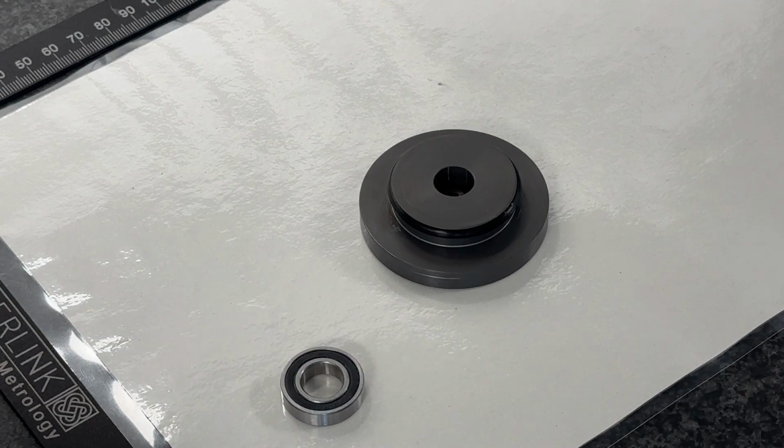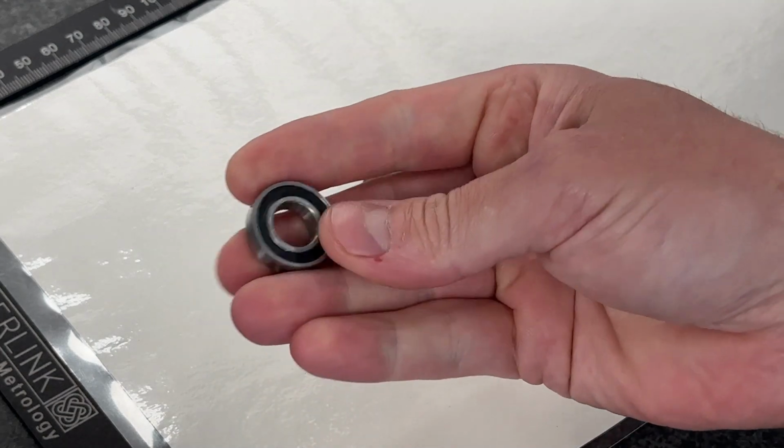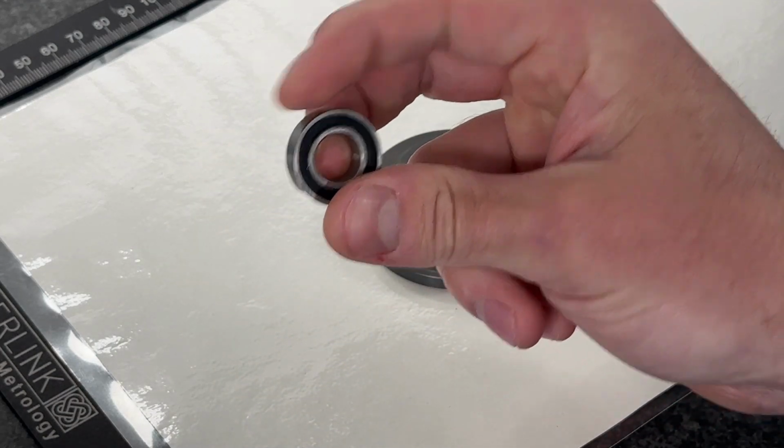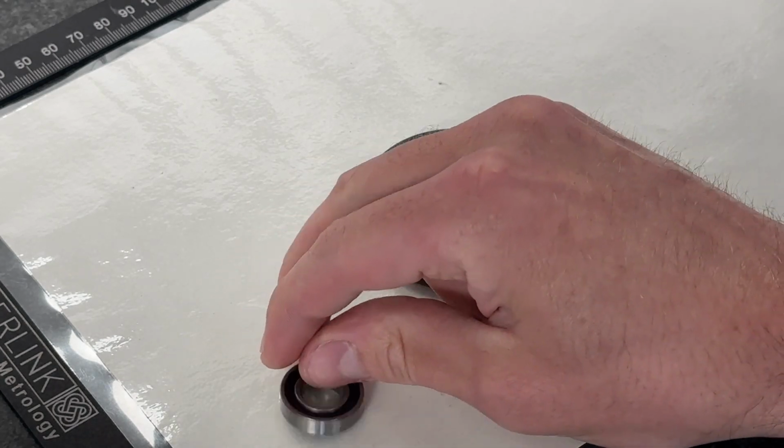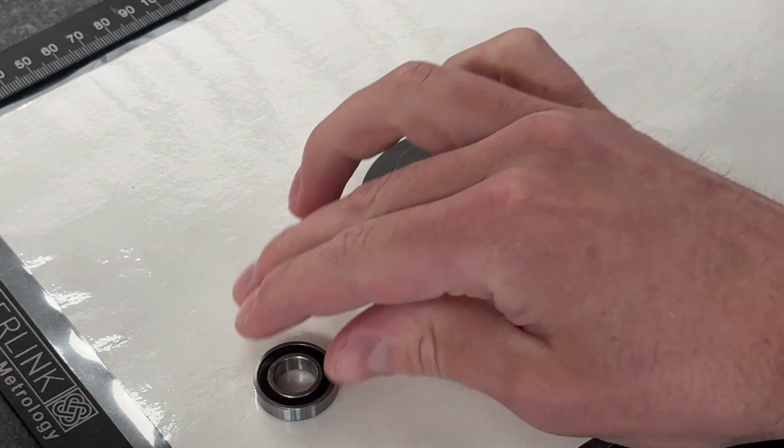Before we get started, I think it's good to cover some basic examples of where concentricity is easily measured and easily applied. Aberlink3D treats concentricity as a 2D size, meaning it can only be dimensioned between circles, and those circles have to be projected into a plane. The position will then be verified from one circle to the other. As standard, this is normally applied on things like bearings.